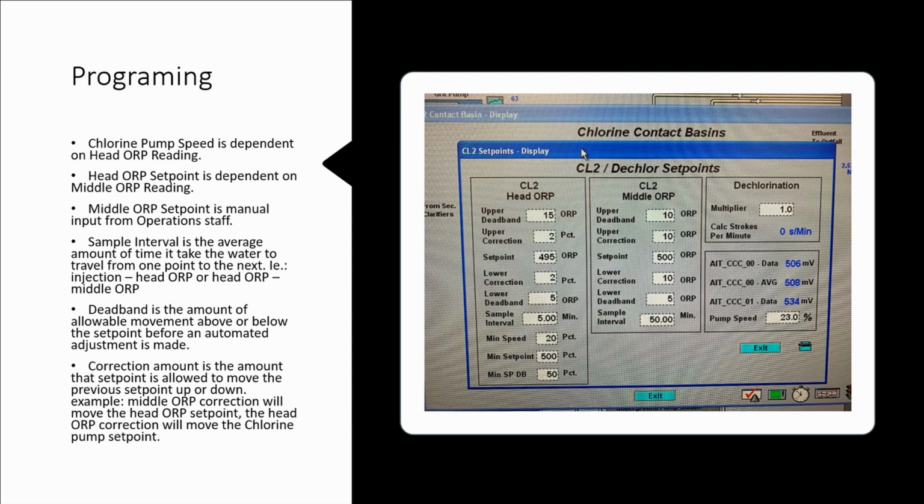So you have the dead band, but then you also have the dampening, which is the response time. So it's not going to try and move until it's at least 5 away. But then when it actually goes 10 away from the set point, it's not going to immediately jump up, and then your pump starts ramping up, ramping down, ramping up, ramping down.